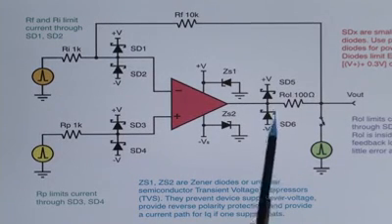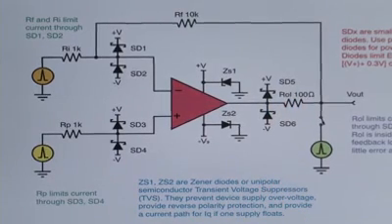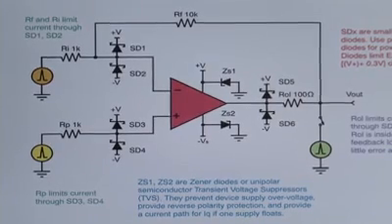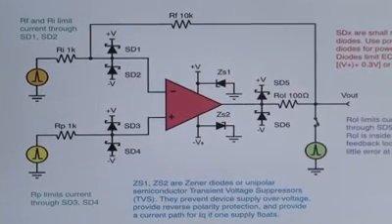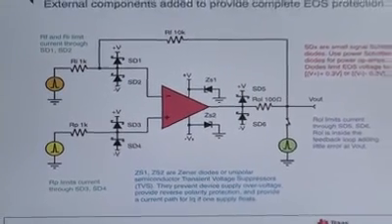This circuit also shows some clamps on the output and a series resistance. That often isn't required, but there have been applications where a voltage was getting back into the amplifier and causing damage.